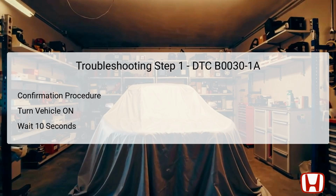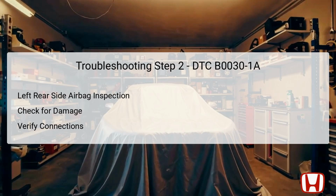If the DTC is not present after this procedure, it indicates that the issue might be intermittent or related to a temporary condition. If the DTC B0030-1A is still indicated, it confirms that a more thorough inspection of the left rear side airbag and its associated circuits is necessary. Maintaining proper SRS functionality is crucial for passenger safety, and this initial step lays the groundwork for further tests. The second troubleshooting step involves inspecting the left rear side airbag directly.